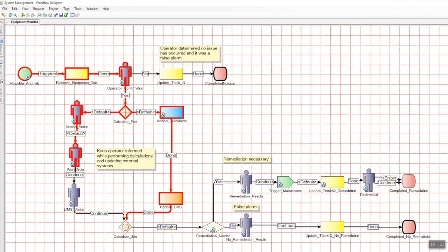As we determined more action was needed, workflow sent the data payload to MATLAB for analysis. Our MATLAB classifier pinpointed and returned the type of the problem, identifying the anomaly as a blown seal. Given this from MATLAB, we knew we needed to take two actions. Workflow interacted with the maintenance system, logging a high priority ticket to dispatch the maintenance engineer to repair that blown seal. It also sent the data payload to the LIMS system to see if there was possible contamination of the produced products.